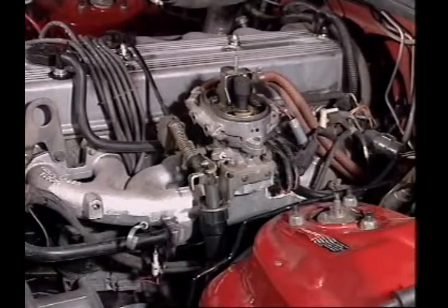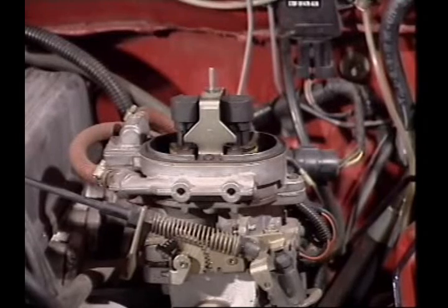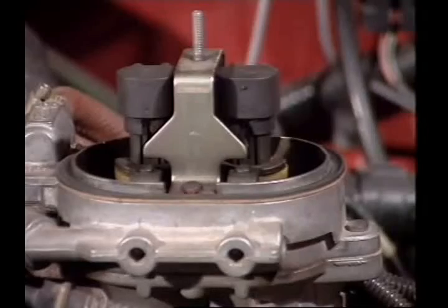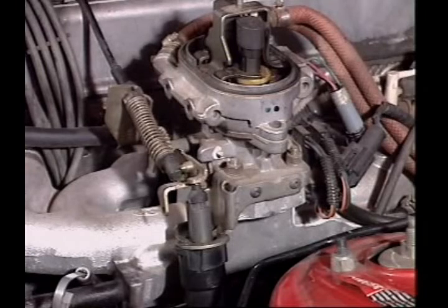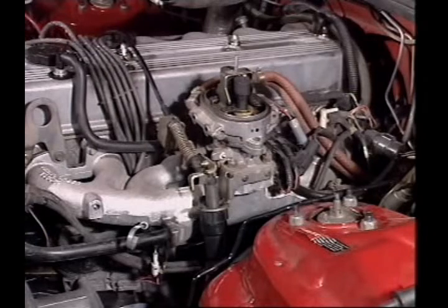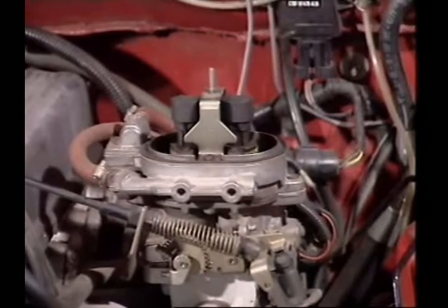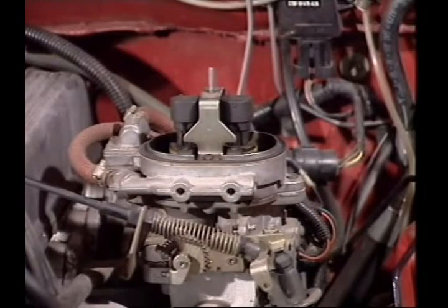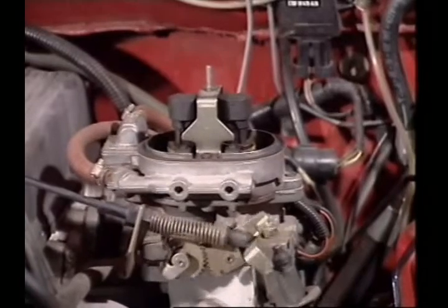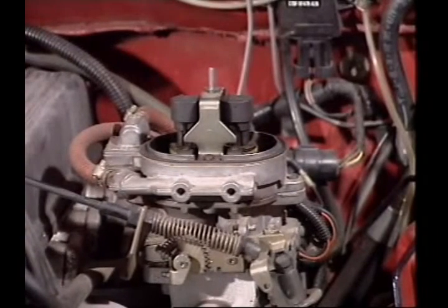The throttle body injection system, also called a central fuel injection system, has a single injector, or in some cases 2 injectors, mounted in a carburetor-like throttle body. The throttle body assembly is fitted to the flange of the intake manifold, and the fuel is sprayed into the intake air entering the manifold. The air-fuel mixture is then carried through the manifold into the engine. Fuel pressure is maintained at a constant value, and an ECU pulses the injector or injectors.